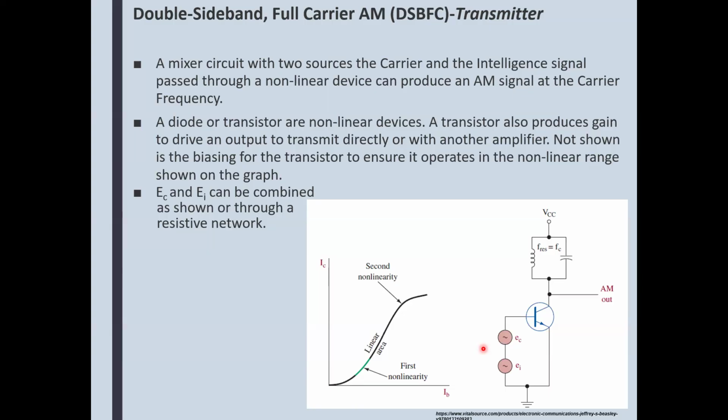Multivibrator. Now, you could have that oscillator oscillating at a frequency that is lower than this tank circuit is tuned to, as long as it can produce a harmonic that this tank circuit can pick up, and boom, there you go. It just amplifies that.